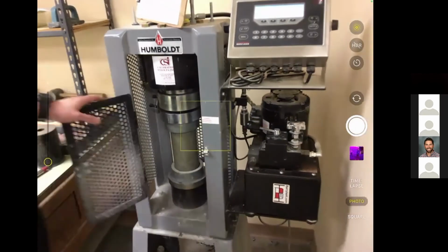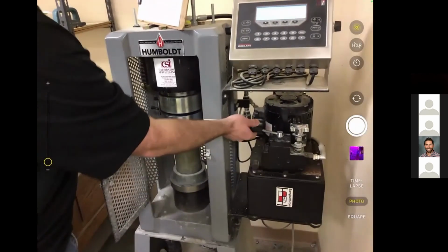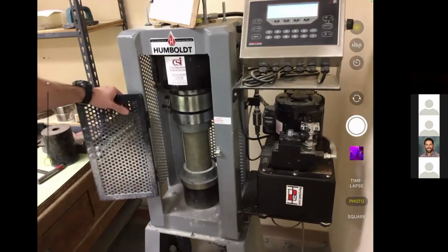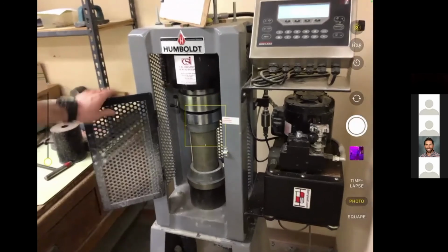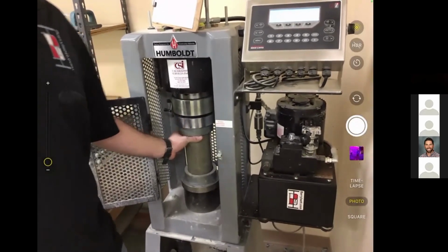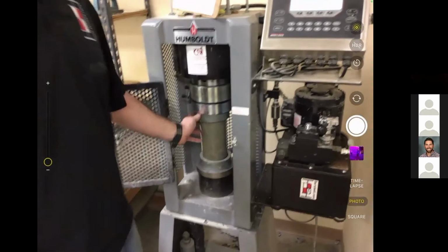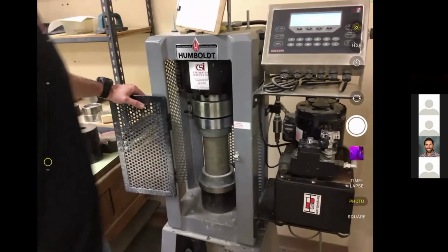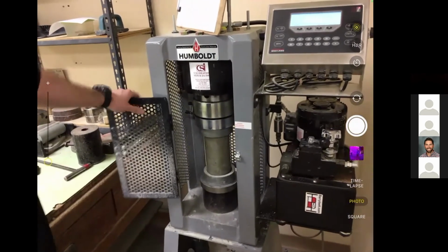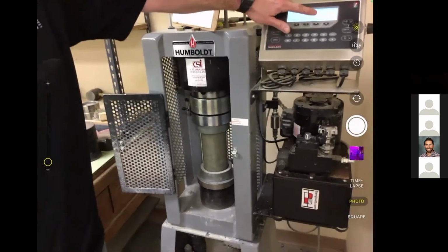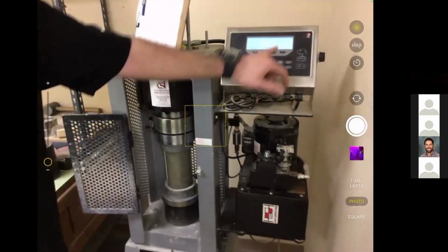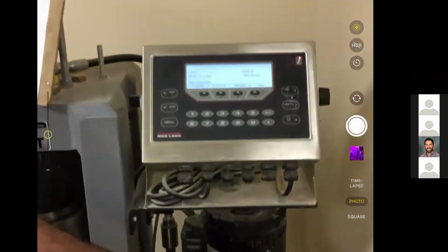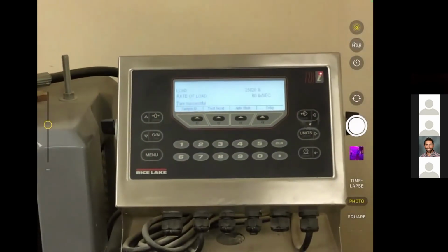So as you go into break, you go ahead and take it to full advanced. And per the ASTM, you are allowed to run this up to 50% of its anticipated strength. So when this cylinder was molded, they used 4,000 PSI concrete. 4,000 PSI concrete needs to reach a total load of 50,000 pounds. So we would run that up to 25,000 pounds here on the screen. Your top number is your pounds, the bottom number is your speed. As soon as you hit 25, you back it down to what's called a metered advanced.